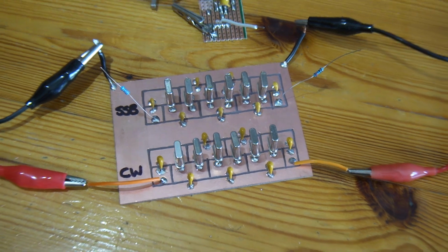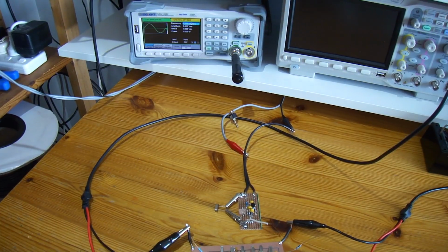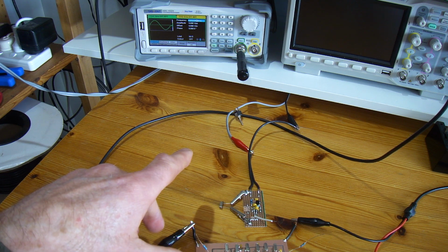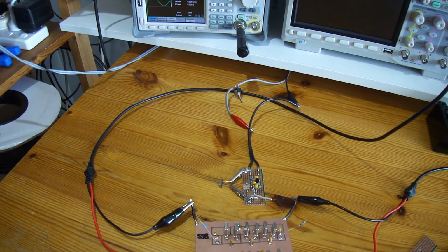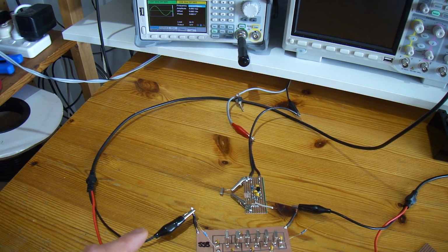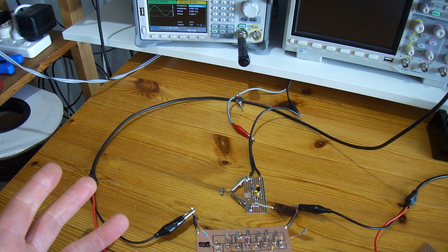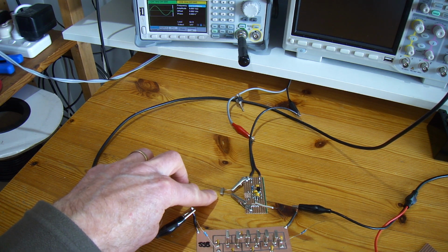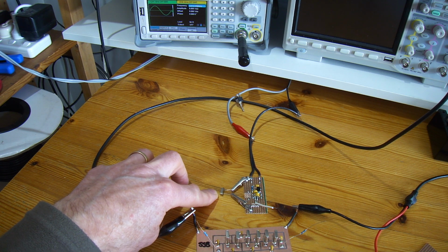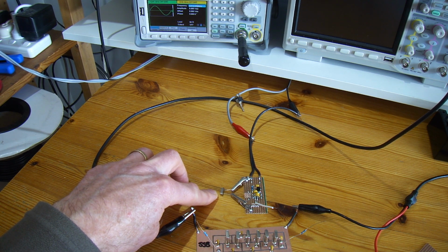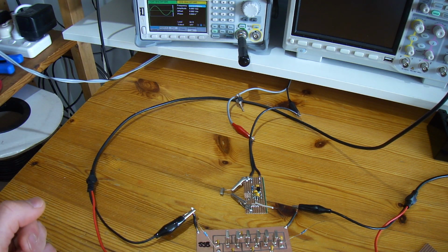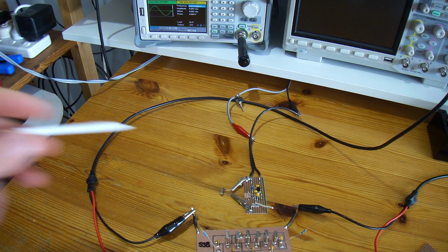So I think I've rambled on long enough there. And like I say, this approach is not for everybody. It's a very simple approach with these crystal filters, but like I say, for me, they have worked in the past. And I do need to acknowledge that in this particular case, with the 4.9152 small profile crystals, which others have used very successfully in crystal filters, I couldn't get it to work with a simple approach. And like I said before, that may be a candidate now for a more rigorous approach.